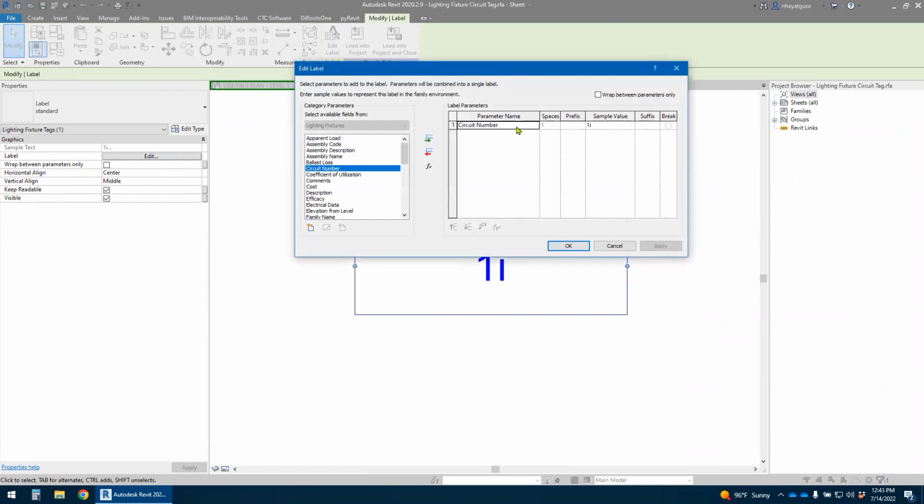That light fixture was uncircuited and it was trying to show me a circuit number. So circuit number is great. I need that shown, but I also need the panel, you know, in order. I need panel like L1, no, it'd be H1, and have a dash, right? So I need it to show me that, but I also need it to show me the type of the fixture.